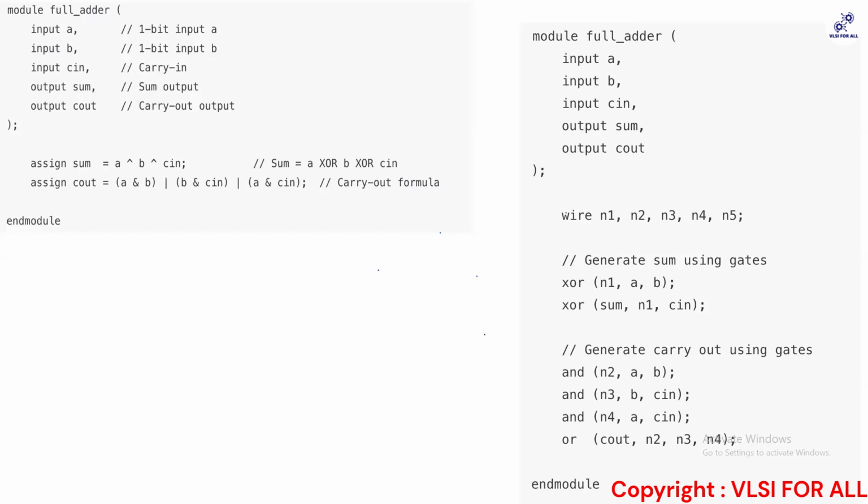The complete way the netlist will be generated depends upon the optimization strategy. It never guarantees, for example, A XOR B XOR C in C. Let us say, by mistake, my library doesn't have an XOR gate. It has only two universal gates, right? Can't I design an XOR using an AND gate? You would have done it, right?